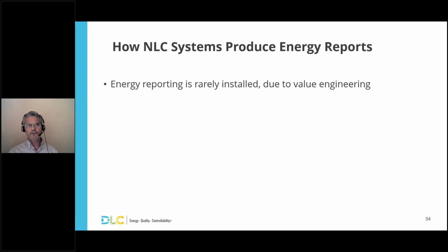To explain this a bit further, while the energy monitoring capability is required by the DLC to be available on non-room-based NLC systems, this capability is rarely a standard feature that's included in every installation of that product. More typically, it's an optional feature that is often omitted from projects due to value engineering.